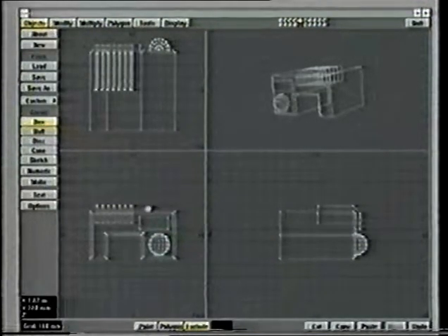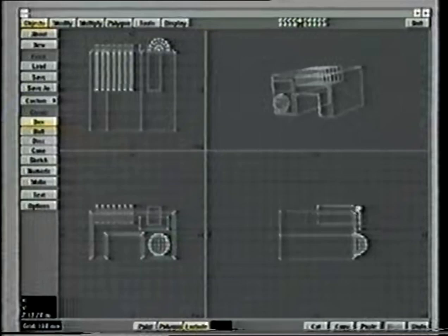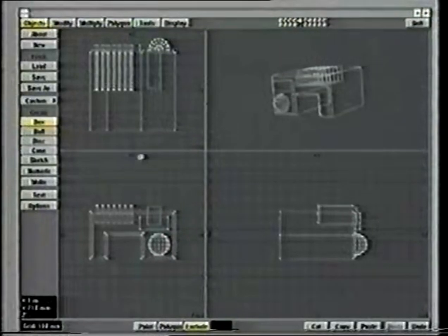You can just go crazy with this. The thing is that there is no limit to the amount of detail you need to put on it. It's just governed by the shot. If you're going to get really close to something, then you've got to detail the hell out of it. Otherwise, try and keep it as sparse as possible, because then you don't run into any aliasing problems which you get when you have lots of minute detail. And also it saves on your polygon count, which means your rendering times will be a lot less.